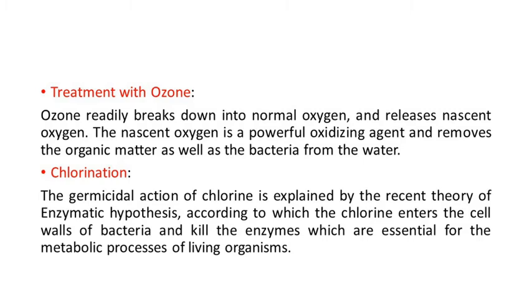Chlorine is one of the major disinfectants which gives protection against contamination of water during the distribution system or during retention. After the addition of chlorine, the residual chlorine is left in the water and it is harmless and still useful in the water distribution system.